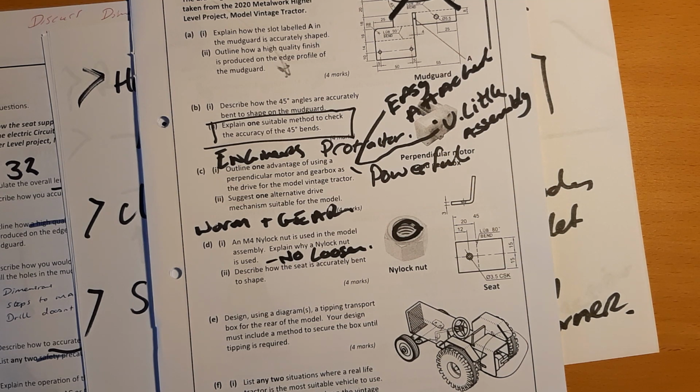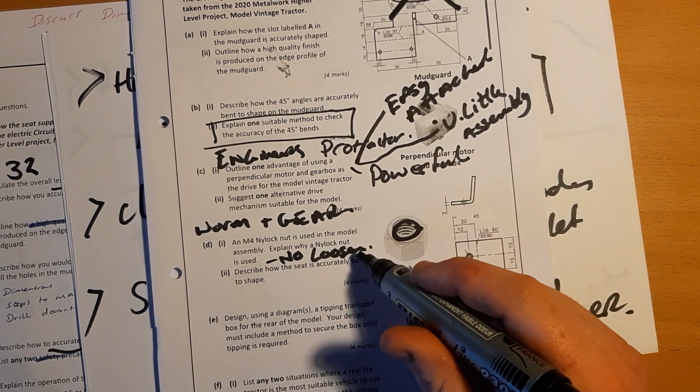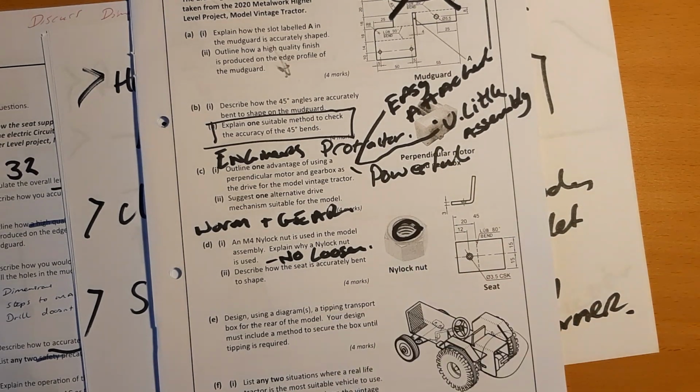Especially because there's a lot of movement. Anything that's pivoting needs to have lock nuts. If you're locking it tight so there's going to be no movement, a normal nut will do. But when there's a bit of pivoting, you need to make sure there are lock nuts, because these will not loosen. Well, they will loosen, but it takes a good bit of effort.